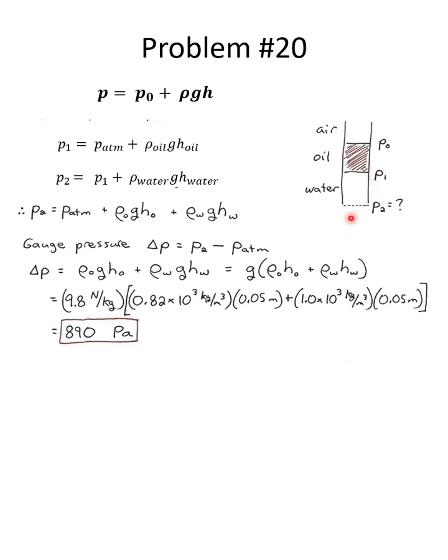Now, there is an absolute pressure, and that is the pressure from the water plus from the oil plus from the roughly 60 miles of air up above. The gauge pressure then is all of that minus the pressure from the air. We go to this basic equation right here that says that the pressure at the bottom of some fluid is the pressure that is being pushed onto the surface of the fluid plus the density of the fluid times g times h.